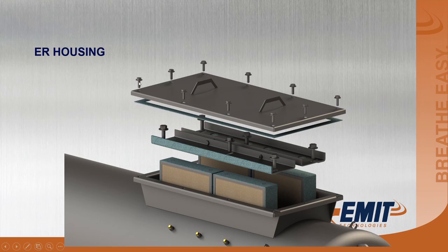ER housings. The ER housing, it's a dual pass, and typically for a rich burn, although it could be used on a lean burn, but back pressure is usually your constraint to keep you from doing that. The gases pass through both sets of elements, so they come in on this side, go through the catalyst elements, and then pass through. These are great for achieving very low emissions numbers. Incredible performance on these units.